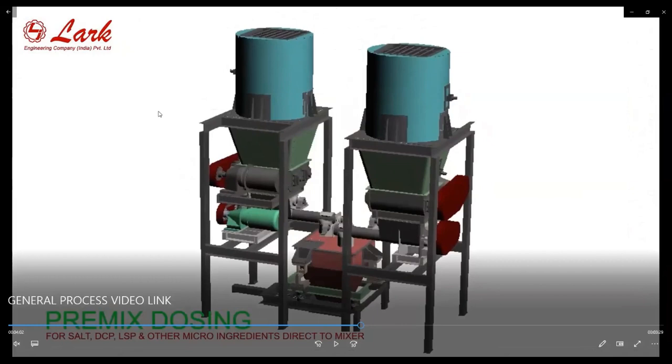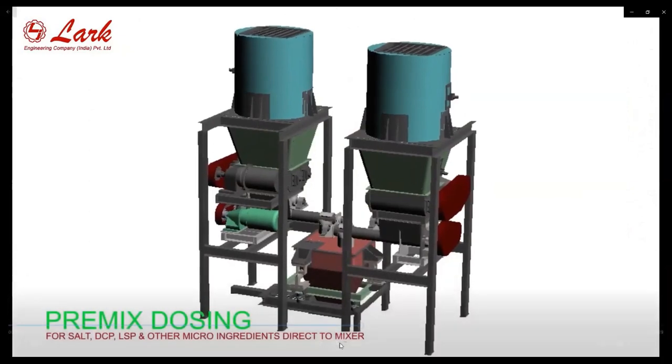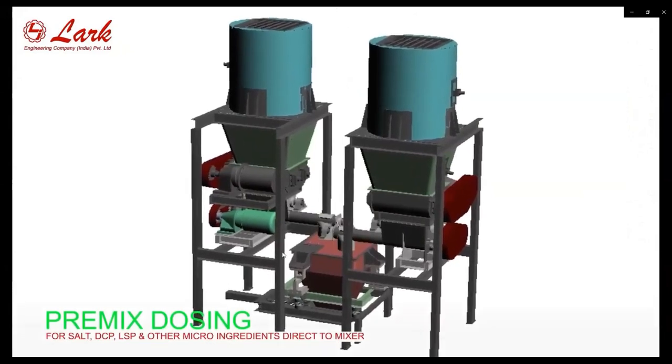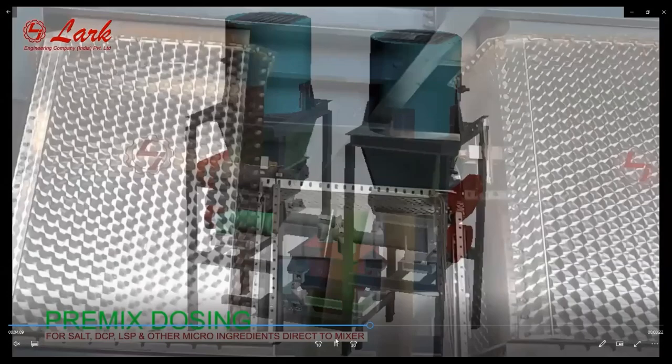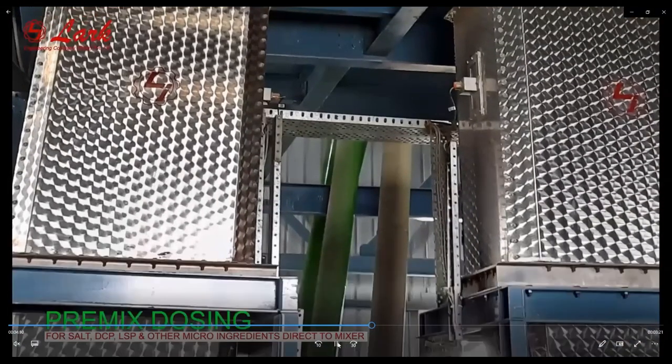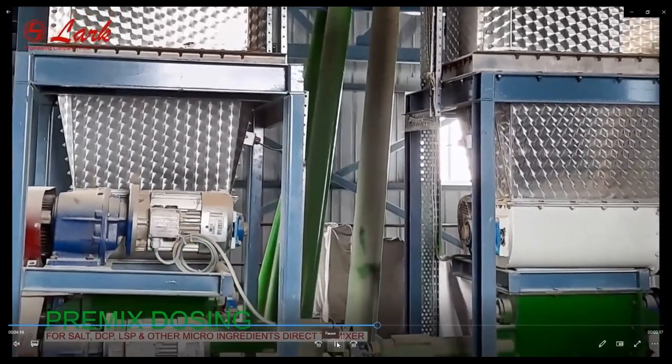These are the premix. For example, we have to dose the DCP, LSP, common salt, or other items directly to the mixer. These are the premix dosing bins that can automatically dose the required premix or medicines or DCP, LSP, common salt directly to the mixer with the help of the PLC and the load cells. Everything for the medicines and the salts is specially designed in stainless steel 304.